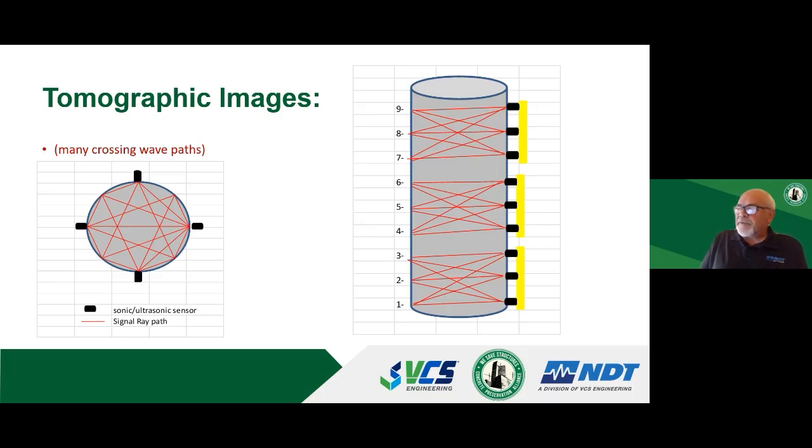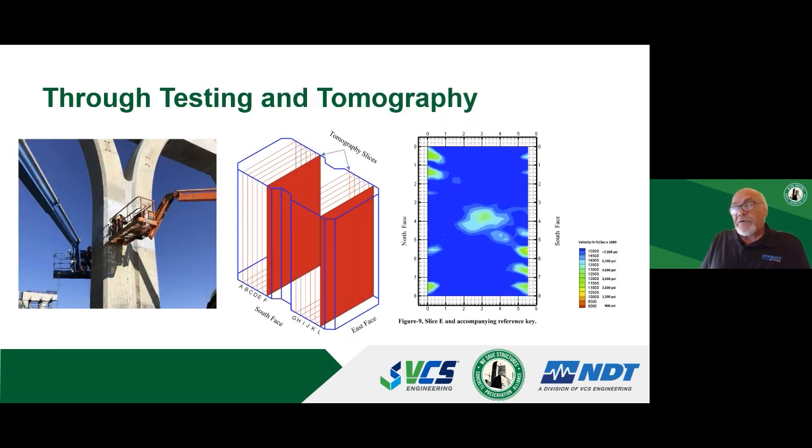It takes a little bit more time in the field to collect all the data. It takes a little bit more time in the office to analyze all the data, but it is an effective way to get the internal core strength of some concrete areas if we're looking at preserving and rehabilitation. Or if there's new concrete, like in this closure pour, there were precast members on the bottom, precast members in a Y section on top going to the superstructure, but a closure pour with an awful lot of reinforcing. And there were some questions of whether there were some consolidation issues within that closure pour.